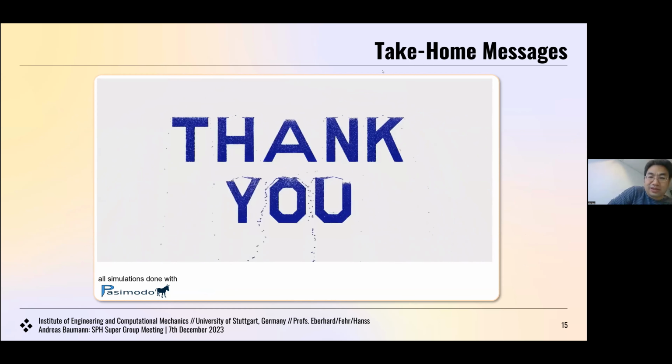No, we have a free surface model. Usually in our simulations, we ignore the gas phase. This is exactly why we need a good surface tension model to capture that. Our solver would also be capable of discretizing the air with particles, but in most cases we don't do it for the sake of a speed up.